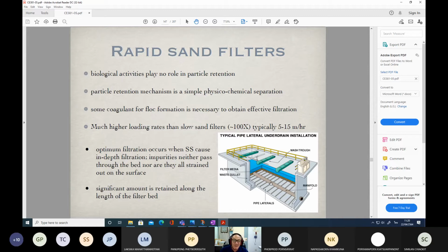This process we normally call a backwashing process. We call it backwash. Okay. So wash through is necessary during backwash. So water just moves up, just like in the case of the sedimentation tanks. Water gets into the tanks from the bottom and then moves up and overflows through the wash through channel. So the water containing a lot of dirt will be collected in the wash through channel. This is the process we normally call a backwashing process.